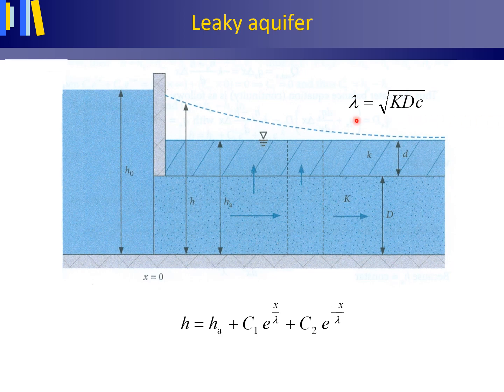The leakage factor is large when the aquifer has a high transmissivity, or kd-waarde, and when the hydraulic resistance C of the confining layer is also large. Horizontal groundwater flow through the aquifer then dominates over the vertical seepage through the leaky confining layer, and as a consequence, in this Hollandse profiel, the hydraulic head in the aquifer, H, then diminishes relatively slowly with distance x from the left canal.